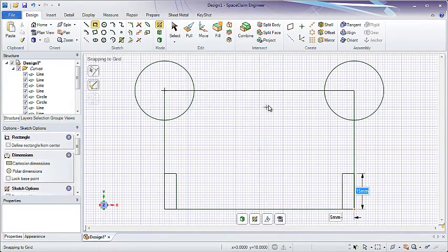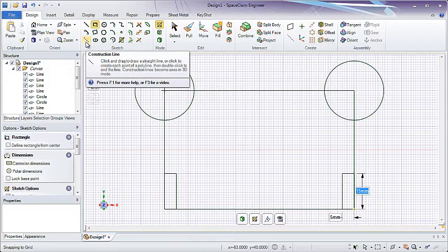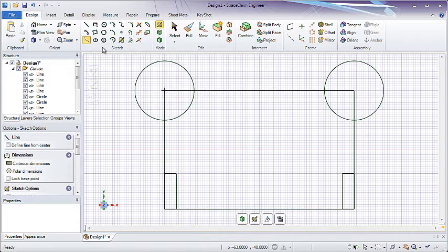Now, you might have noticed that everything we've been creating so far has been symmetric. A lot of times people will sketch only one side of your sketch and have it mirrored to the other side. To do this, I commonly create a construction line. And what I'll do is make a construction line bisecting the model. Notice the green triangle near my cursor. By clicking on that green triangle, it'll let us snap to the center of the line.